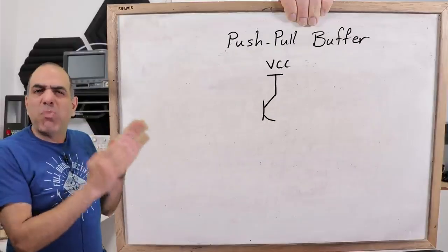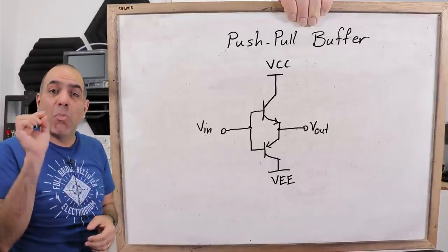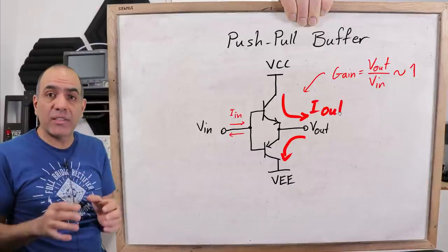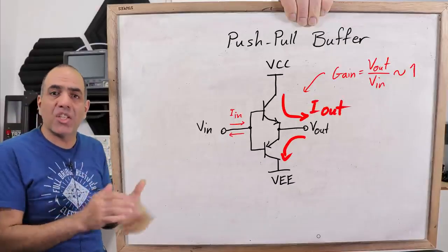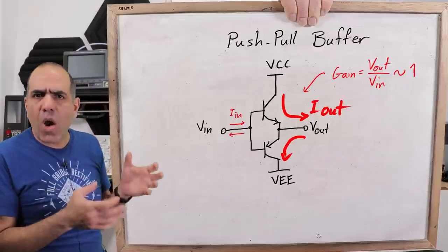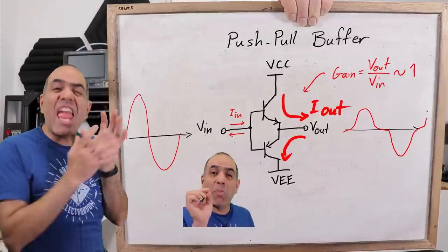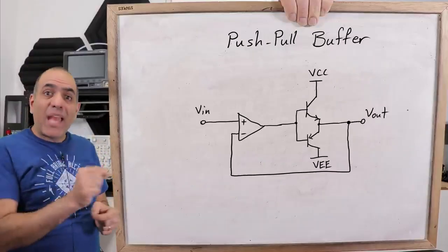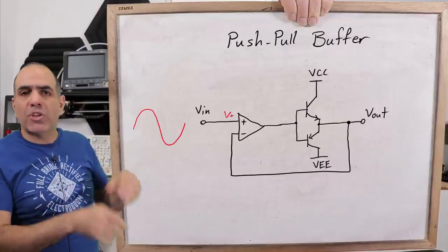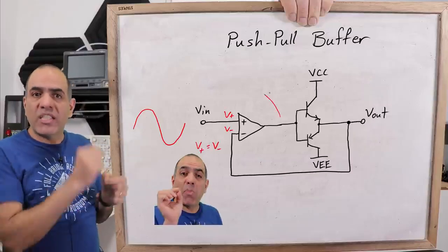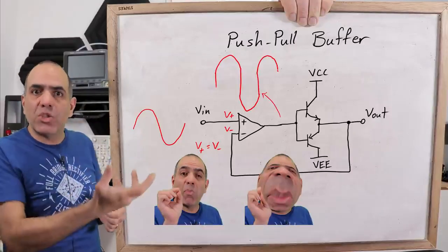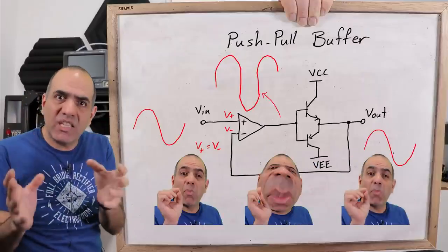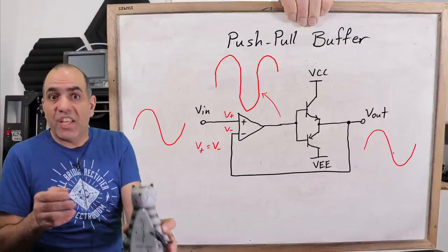Take this transistor push-pull circuit. You use it to buffer. It draws small input current and outputs massive current like in audio amplifiers and such. Its gain is around 1, but it distorts the signal heavily by cutting the midsection. You add an op-amp to it with feedback from its output. The op-amp, trying to keep its inputs equal, sends signal with an inverse distortion to the push-pull buffer that passed through it creates the same signal as the input. Huge gain is awesome,